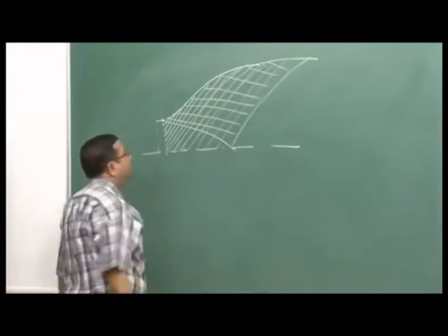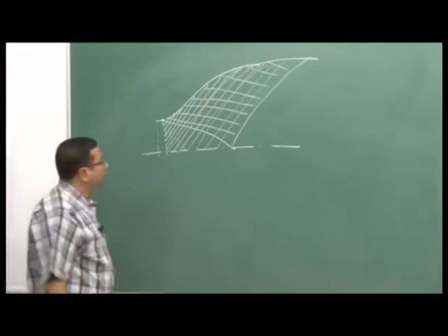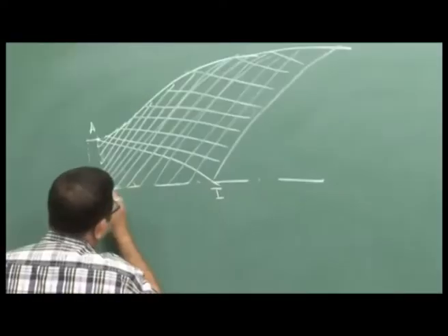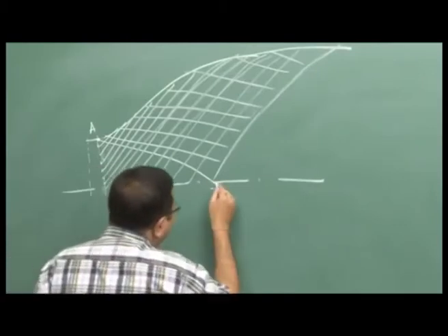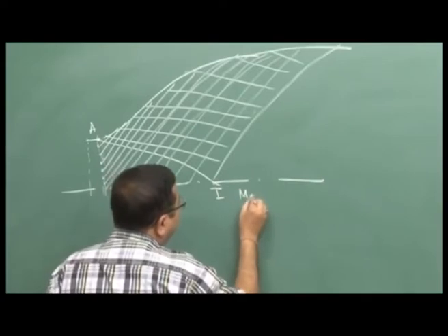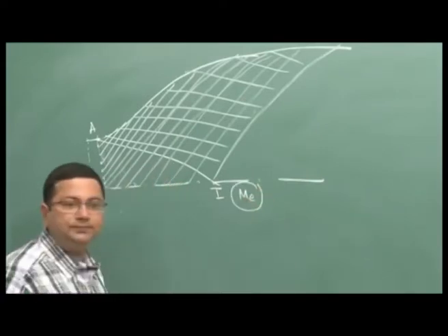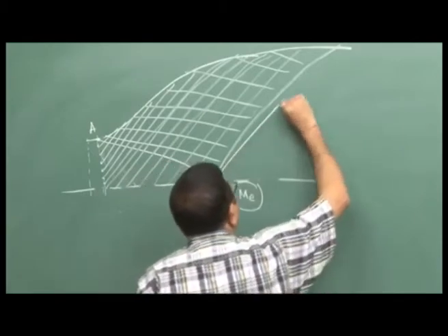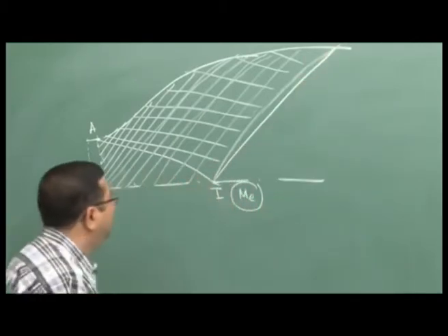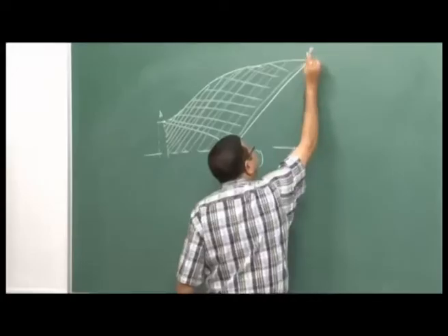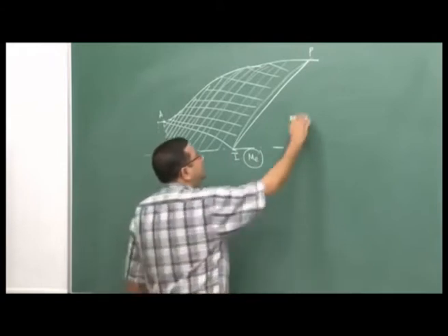So, these are all Mach lines emitting from different locations. Then first we solve in this domain till we get to the point I, where the Mach number is our design exit Mach number. Once we get to the design exit Mach number, we drop a Mach cone from here based on this Mach number, and we get the length of the nozzle now.